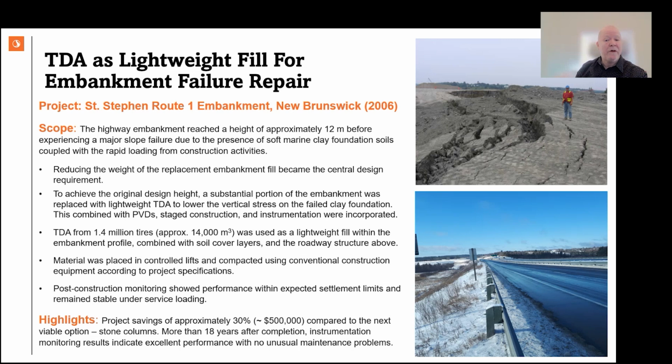This project involved repairing a major highway embankment failure that occurred during construction over soft marine clay. The photo on the top right shows the deep-seated failure that occurred. And because of this big failure on marine clay, we needed lightweight fill. So reducing embankment weight became the controlling design requirement. Lightweight TDA was the solution in combination with stage construction and geotechnical instrumentation.